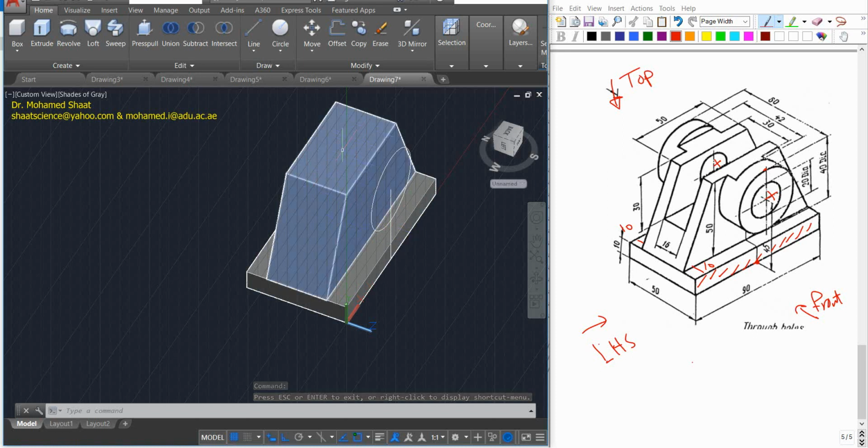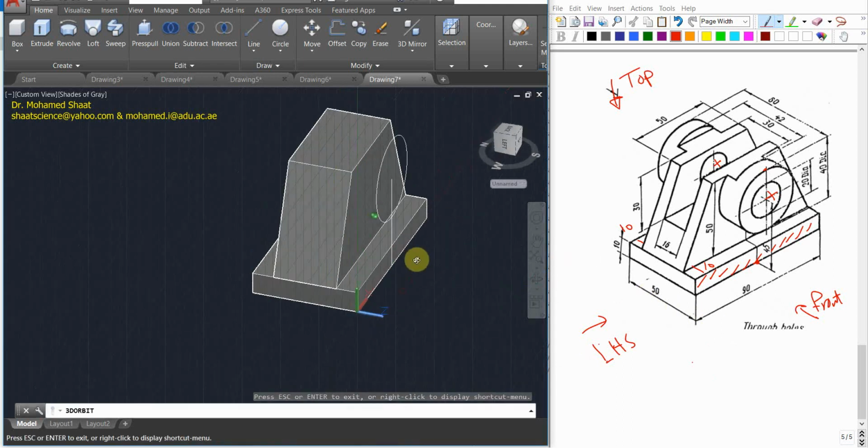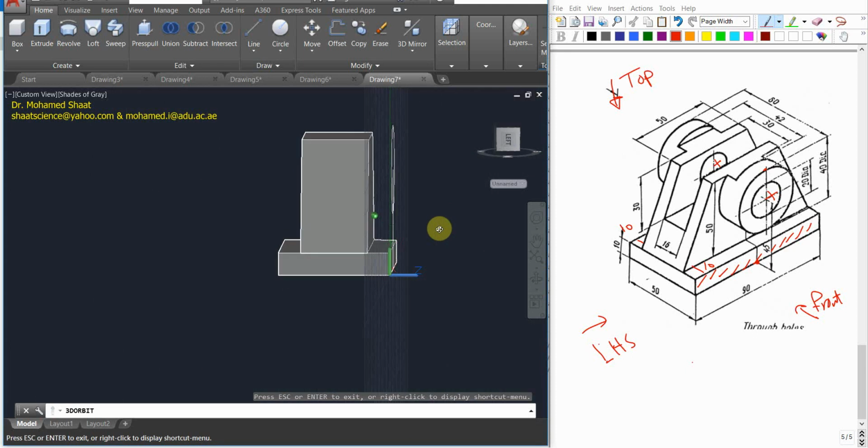If you decided to move it back to the midpoint, you have to draw a line here, and this line should be going inside the shape as already seen here. It should be in the middle, because the width of the base is 50. If I give it an orientation in this direction, as you can see, I have to move it back by half of the 50, because this entire distance is 50, so it should be in the middle at 25, right?